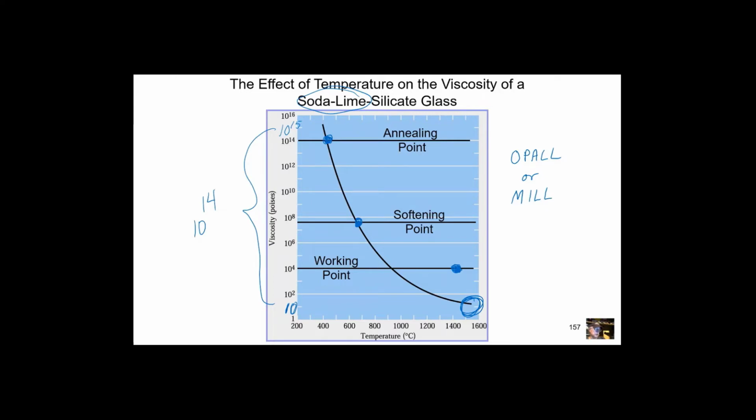And what you'll see is that when you're done with doing something like that, you leave it at a high temperature. So if you take a piece of glasswork into the glass shop, Georgia Tech has an actual GT glass shop, which is over there in the environmental science building. And if you take them a job and they put two pieces of glass together to make a reactor or anything, they won't give it back to you until they've held it for a day or two at this kind of medium-high 400, 600 temperature range. And they anneal the glass and give it time to work out any stresses that are built up from putting two pieces together. You may not get a total equilibrium.